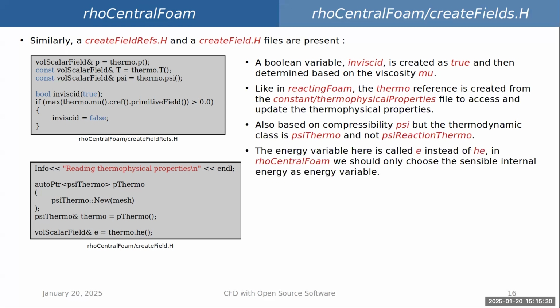Additionally, the thermodynamic class used is psiThermo, not psiReactionThermo anymore, since rhoCentralFoam focuses on compressible flow without chemical reactions. However, in rhoCentralFoam, the energy variable is referred to as e, the sensible internal energy, instead of he, the sensible enthalpy. So in rhoCentralFoam, there is only one way of solving the energy equation, and it's in terms of sensible internal energy.